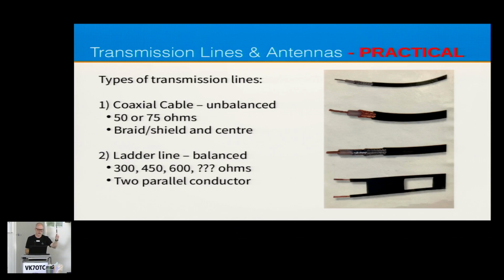The way to think about it is, if there is some sort of interference or some sort of external signal that is cutting across this particular line, it cuts across both lines equally. And so, in the configuration of the antenna you've got, that signal gets nulled out because it's actually on both sides of the balanced line. So that's why we call it balanced line.